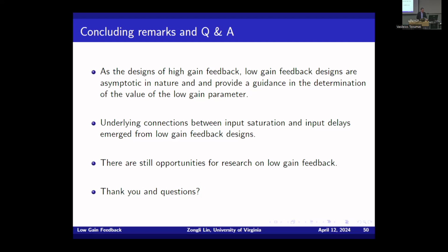One reason is that observer output or sensor feedback is much harder to deal with. Because with input feedback, you have Fx to be saturated, but I have a choice to design F. But for the observer, with sensor saturation, you don't have control of the sensor.